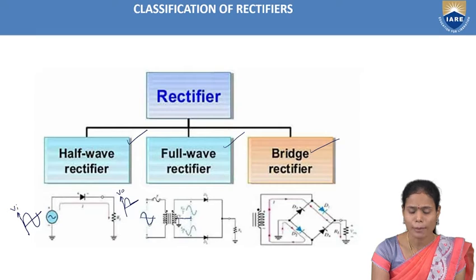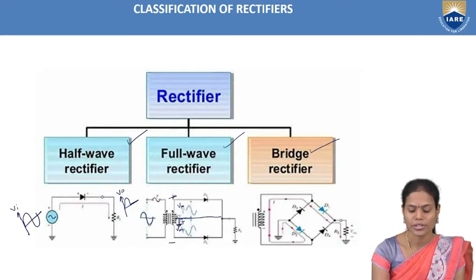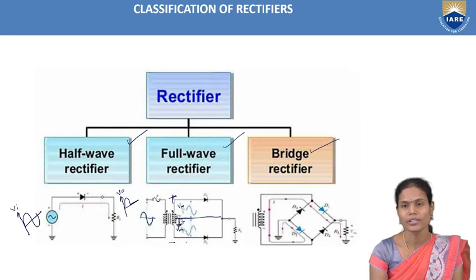That will separate the secondary winding into two windings. So whatever voltage is applied from the primary will appear here as Vm, and one more Vm here. Suppose here it is positive, meaning positive to ground, and here it is negative, meaning negative to ground. Why? Because this center tapping wire is grounded here. So positive voltage will go here and negative voltage will come to the second winding of the secondary winding.